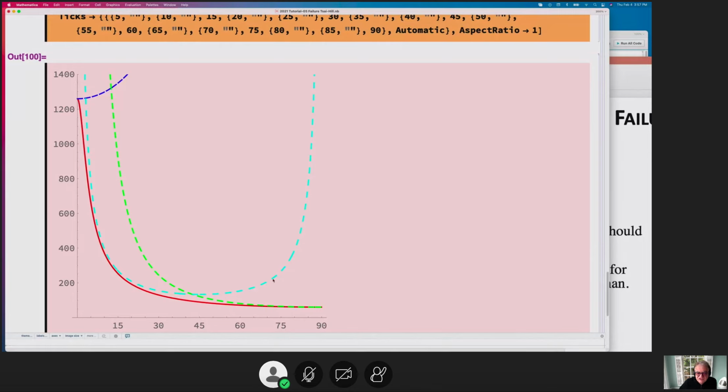This is the shear. If I look at only shear value, failure is due to shear, this is how my curve changes. So, in fact, if I ignore the red line and make my failure based on max stress for fiber orientation, it will tell me that by about 2-3 degrees, my failure load is about here.